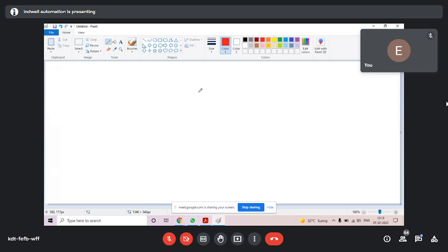It has no physical existence. Outside of PLC, there is no flag. There is no physical existence. And it is a bit memory. Bit memory means it will be either on or off. Like input is a bit memory, input gets on and off. Output is a bit memory, output gets on and off. Flag is also a bit memory, flag will also get on and off. So these three things, input, output, flag, these are bit, correct?